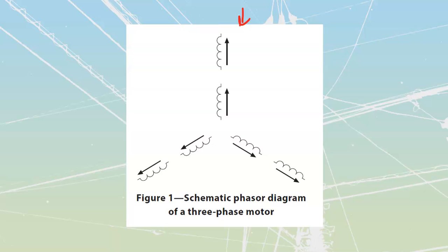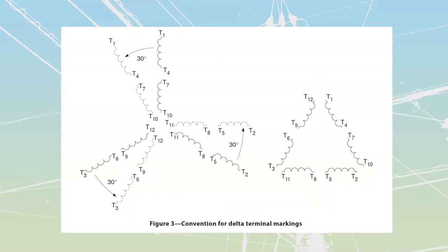If we have a delta connected motor, a delta connected motor is just going to have a 30-degree phase displacement. You do remember this from transformers, because you're all smart like that, whether we have a 30-degree displacement anytime that we're going from Y to delta. We're going to use what's now been placed into these to build a triangle out of that. Don't worry so much about doing the 30-degree displacement. Just start by building yourself a triangle like this and going around it in the same method.